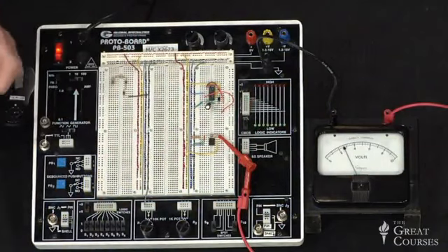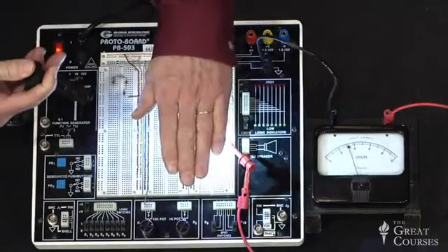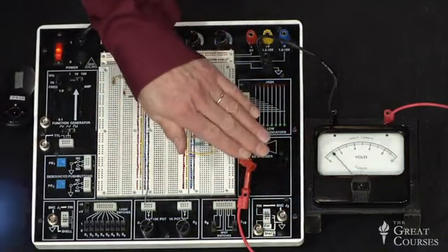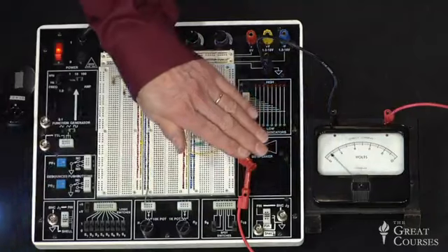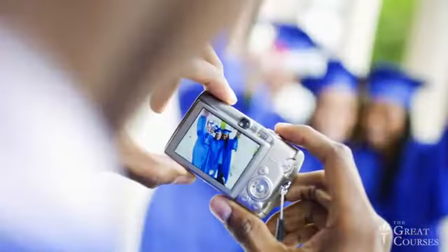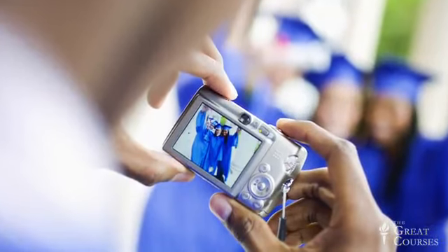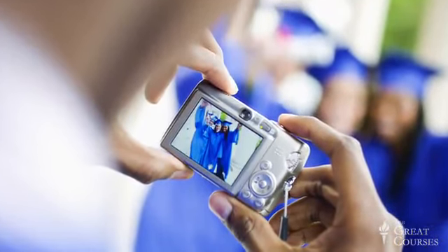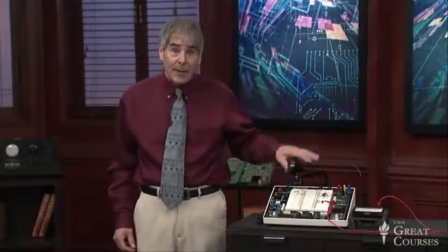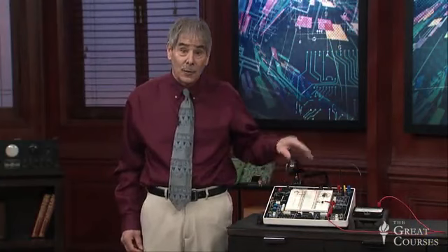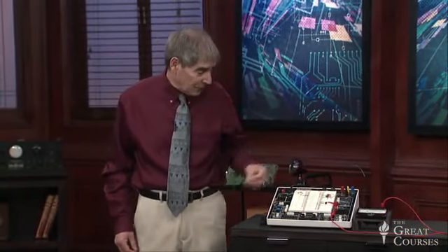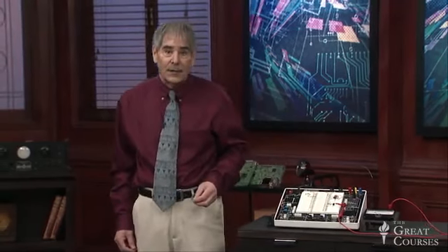And if I were to work underneath a shade here, you probably can't see that too well, there we go. I can go all the way down towards 0 and then sneak that light in, and it goes up quite a bit. So we have a light meter. What's this good for? Well, most cameras have a light meter in them. You don't see the light meter in a modern camera, but it's in there, and it does things like calculate how long the exposure ought to be. So that's a light meter, and it uses a current to voltage converter with a phototransistor as the current source, making a current that's proportional to the intensity of the light falling on it.